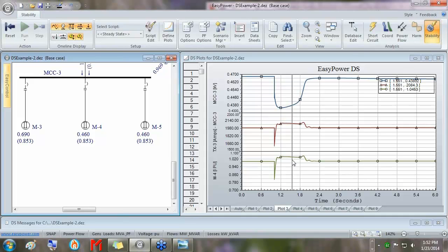That was the last thing I wanted to show you today. We got through from the beginning looking at the data that's necessary, looking at the models and the reason why we wanted the full detailed flux model. From the data, we did a parameter derivation, and when we got finished with the parameter derivation, we did some nice motor starts, and we showed how it's really an important thing. If you have a lot of motors in your system, definitely don't just model the one that you're starting.